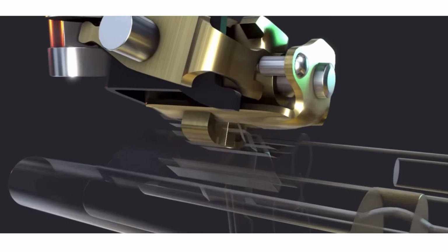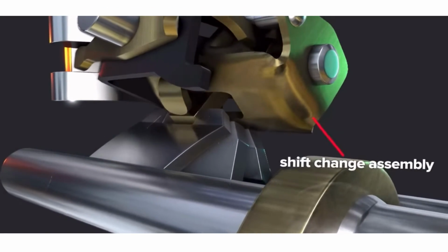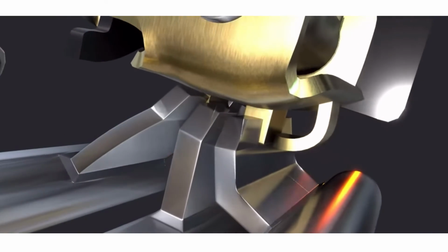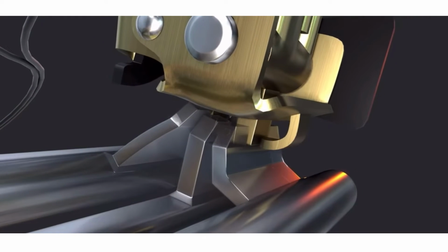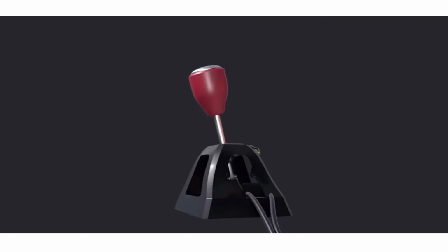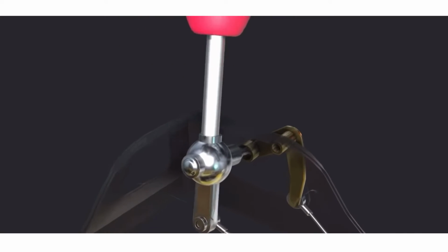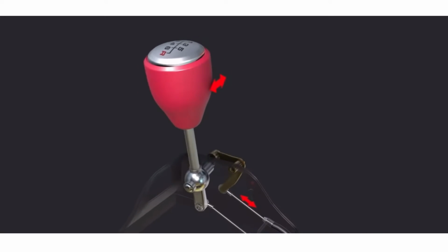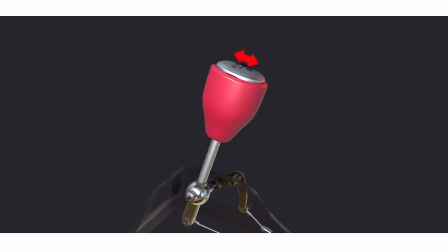Working of modern manual transmission. Today, almost all the vehicles with a manual transmission on the road are equipped with a synchromesh gearbox, as it is more reliable, needs less maintenance, and the selection of gear is not complex with this type of gearbox, whose working is as follows. When the driver presses the clutch pedal in order to shift the gear, the disengagement of the engine flywheel and clutch shaft occurs, which lets the driver select the appropriate gear according to the need of the drive.